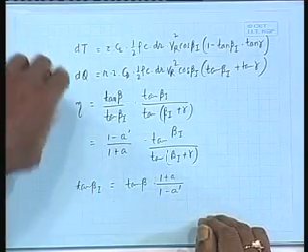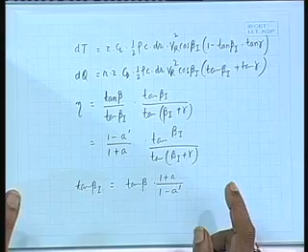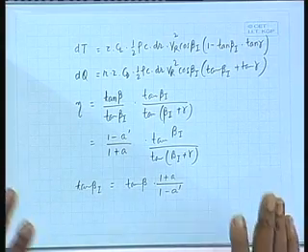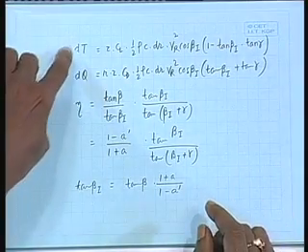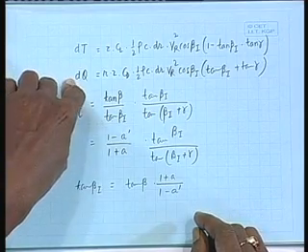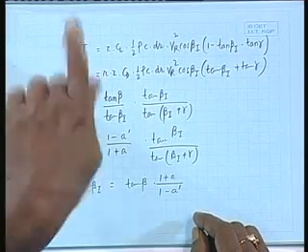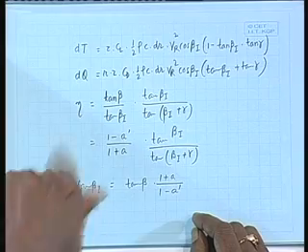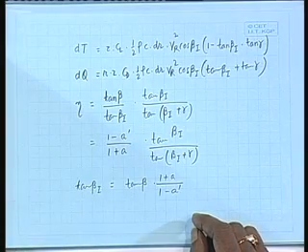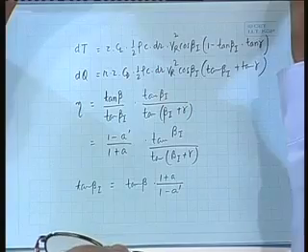What is the propeller efficiency? If we want to calculate the overall propeller efficiency, how would you go about it? We have got the elemental thrust and elemental torque. We have to integrate it over the entire radius, 0 to capital R, right? I can get the total thrust, I can get the total torque. Then efficiency will be same as we have written the formula before.